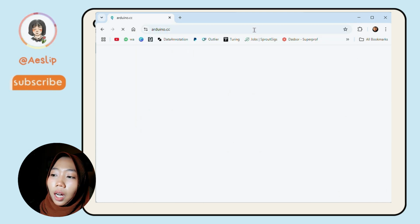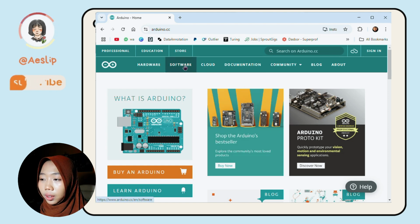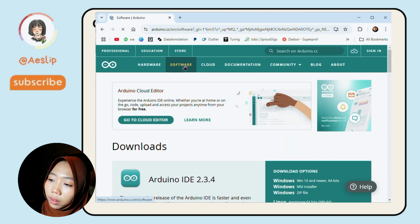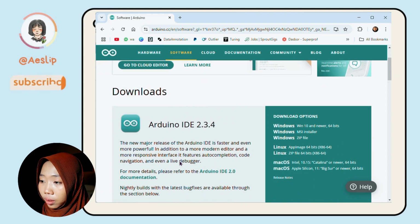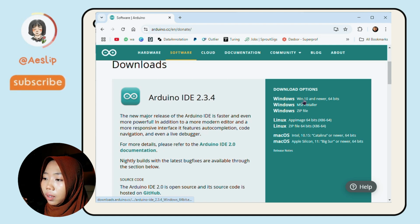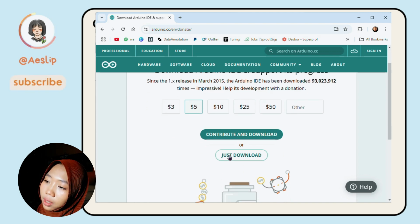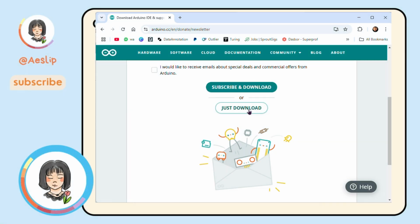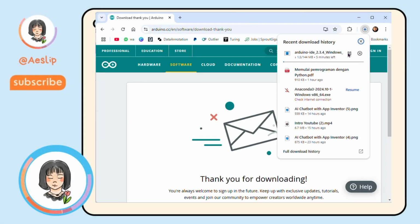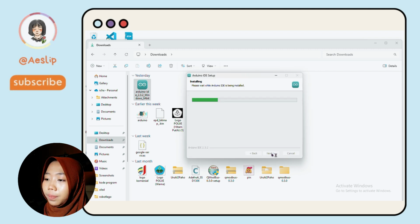The first step is to open the official Arduino website at arduino.cc. Select the menu Software and Download. Select the version according to your operating system, like Windows, Mac, or Linux. Here I use Windows OS, so I will download the Windows version. After the download is complete, open the installation file and follow the instructions until it finishes.